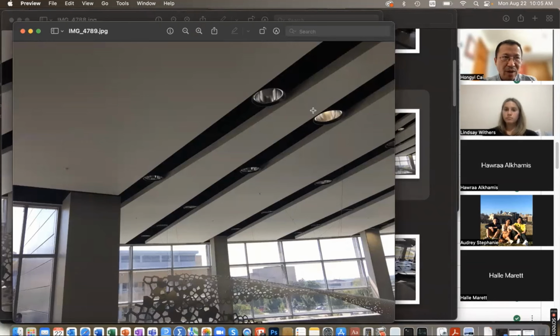A few of them are still on, most of them are on, even with a lot of daylight in that space. And you do not have a switch in the lobby area because the switch is in a control panel locked in an equipment room, which is against the code. I tell you the truth, which is against the code. But anyway, we had this problem.